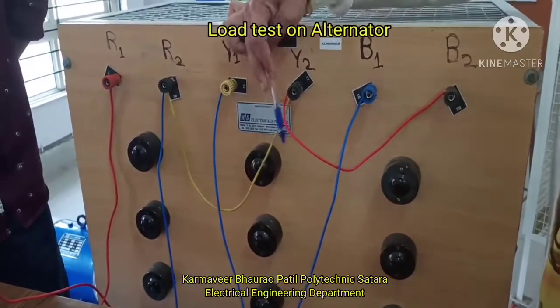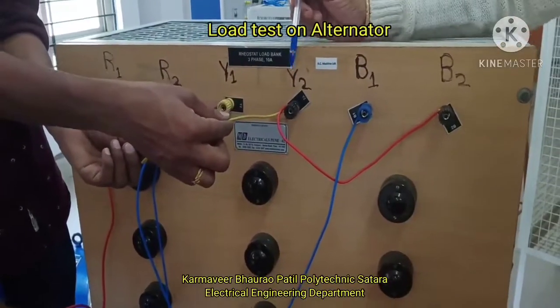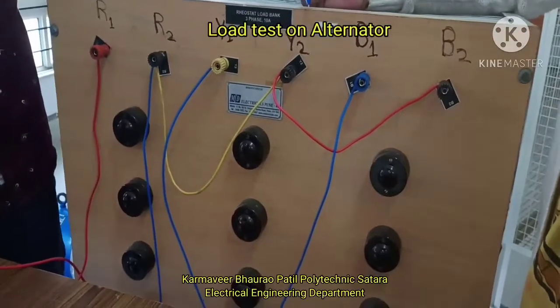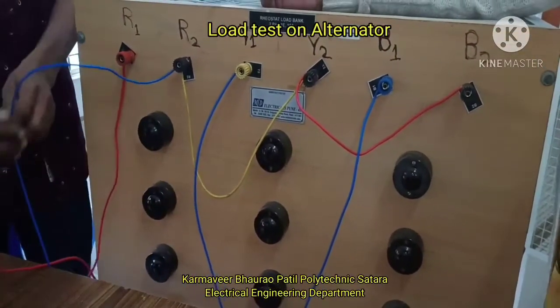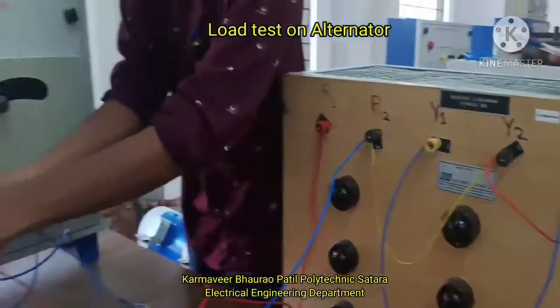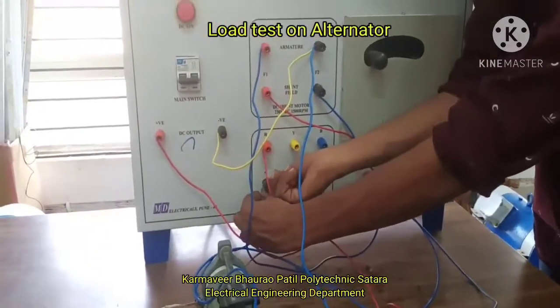You will see this wire, through which we have connected R2 to Y2, then Y2 to B2. That forms the neutral of the starter, and this neutral will be connected to the neutral of the alternator.